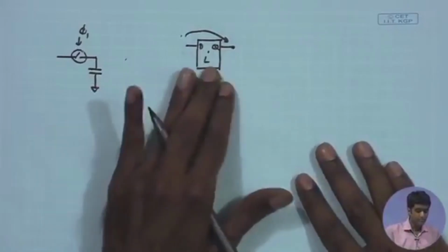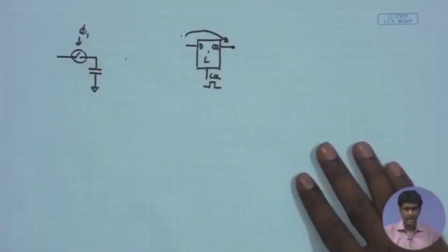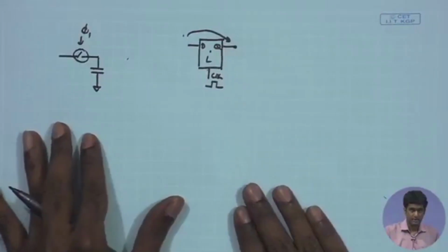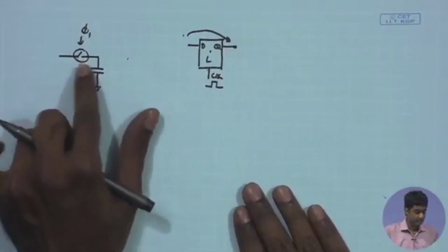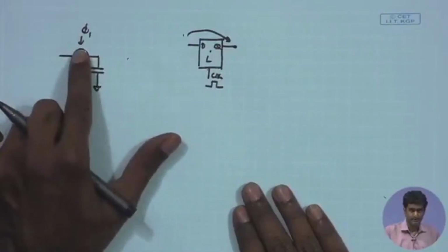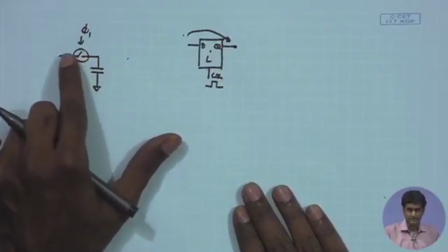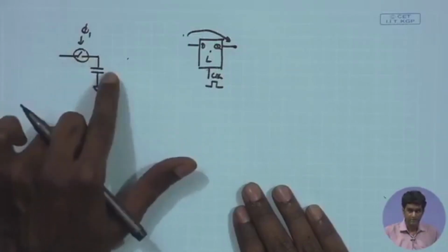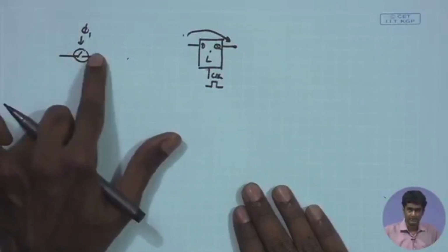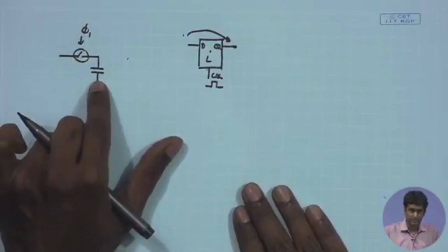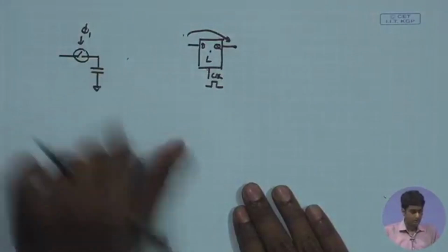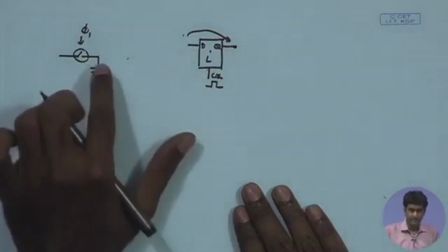So, if we want to implement such a latch and hence the master slave configuration, edge triggered flip flop, the simplest possible implementation would be something like this, where you have a switch and a capacitor. Since this can store analog values, it can as well store digital value. If it is a transmission gate, we can always expect that it can pass VDD as well as ground reliably, and we can have a capacitor over here, and therefore, it can comfortably store the digital value as well, whether it is VDD or ground.